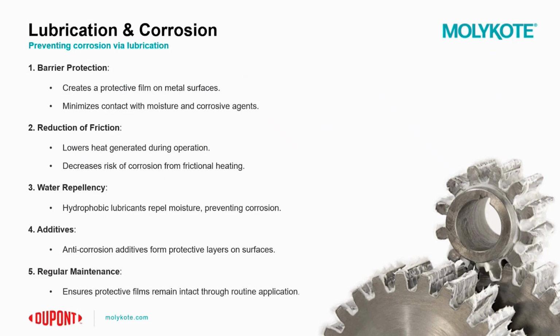And that can be accomplished through a number of ways. One is that the lubricant essentially provides barrier formation. So it provides a protective film on the surface of a metal, and it'll act as a barrier in order to slow down the exposure to moisture and corrosive agents. Additionally, the lubricant will act to reduce friction. And by reducing friction between moving parts, you're essentially minimizing wear and tear. So it's another way to mitigate the occurrence of corrosion.